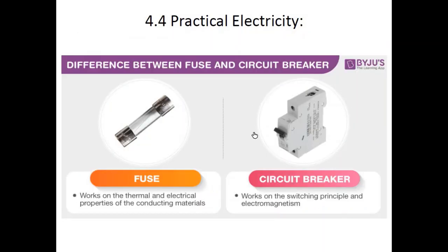You see this, once some excessive current flows in, this automatically falls down. And once you have taken care of the damage, you can simply push it back up and the circuit would work fine. The switch would again be closed and the current would start flowing again.